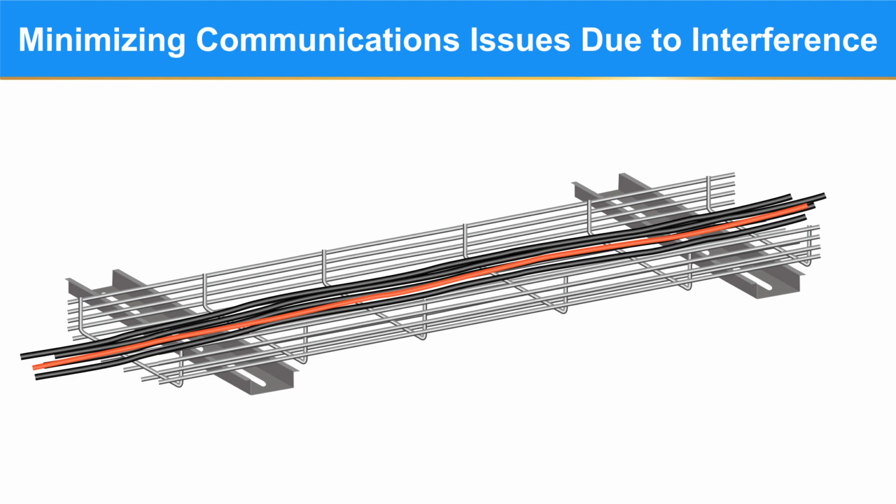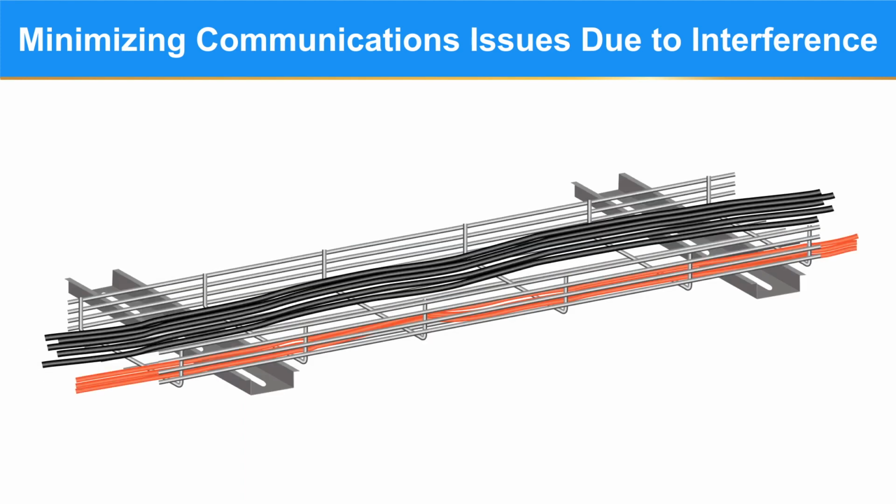One other thing to check is the cable tray the LON network cable is laying in. It is best to ensure the LON network cable is not laying in with other large cables that could possibly be carrying high voltage machinery signals. Having the LON network in a separate cable tray would be ideal, but at a minimum, the LON cable should be as far away as possible from any other large cables in the cable tray.